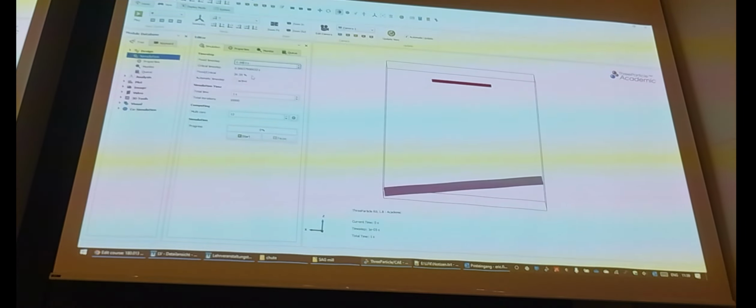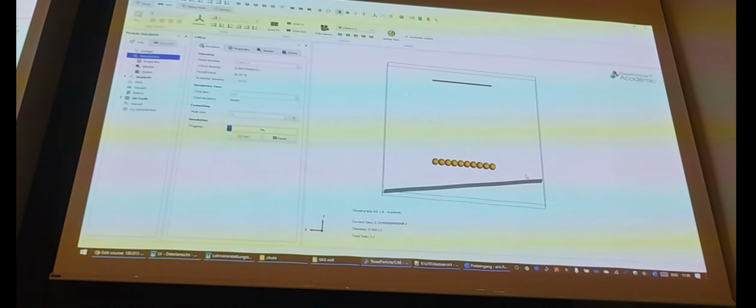So I changed my time step so that here it is about 20%. 26, 30 might be okay, but it's probably not stable anymore. I will show you in a minute what that means. 26 should work. I want to simulate not 1 second, but 5 seconds in total. Again, I save, and I start. And it should be much faster. Yes, particles are coming out. And we have contacts. Perfect, looks good.